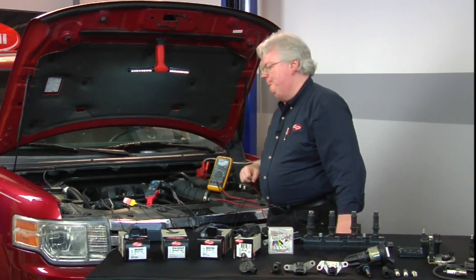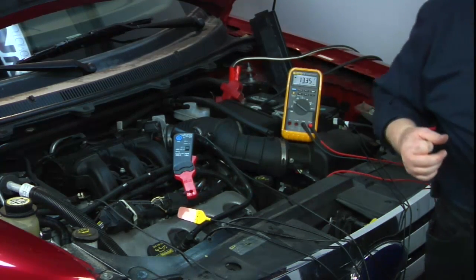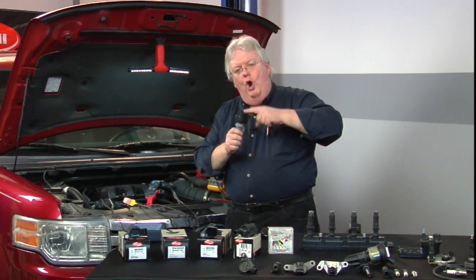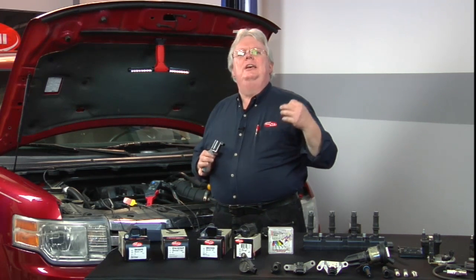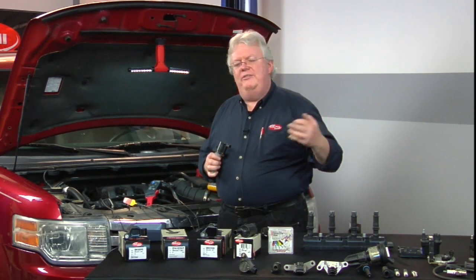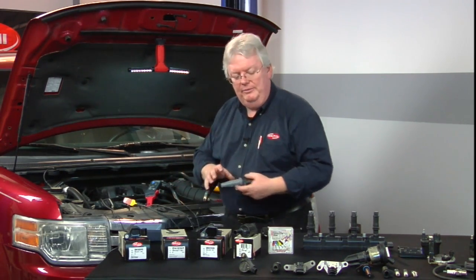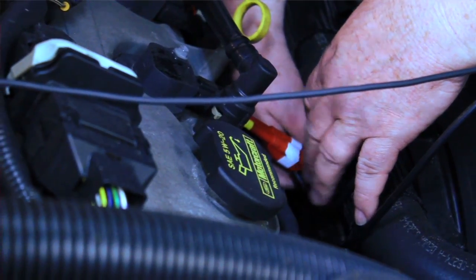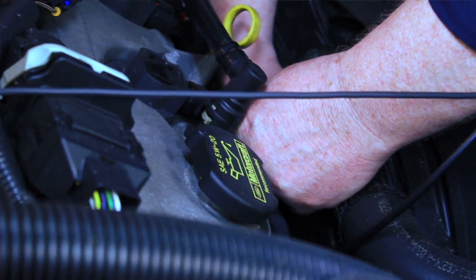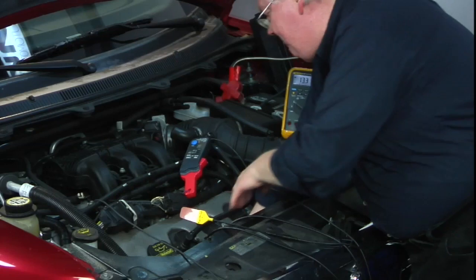Turn the key on. Watch the meter: 13 volts. Now, if you want to see if the coil has continuity, that it's not an open circuit, let's say you had a P0301 on the cylinder and you're not sure what it is. Really quick, something you could do before going in further: air, fire, fuel, which is it? Just check the coil out real quick. It's easy to get to in this model. I'll take the plenum off like some of those back cylinders, and we'll move our lead from back probing the positive feed to the negative feed, the side that gets the ground from the PCM.